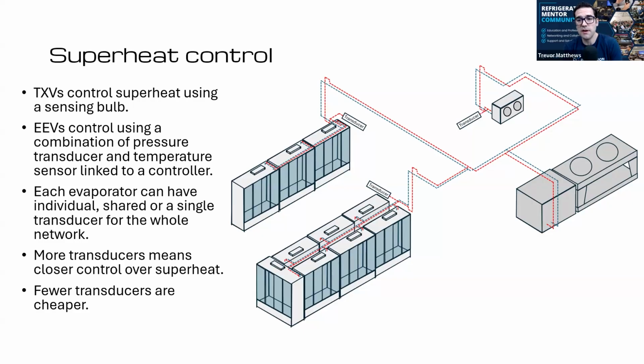Because you've done both, right? And what are your thoughts on the differences? Yeah, so obviously with the new systems, I can dial into a store remotely. On the contract that I was working on, I could look at the fault and potentially diagnose it before the engineer even arrived. It's great for a steer. If I'm seeing flood back, low superheat on something, I can shut it down remotely as well, protecting the compressors, because obviously there's a big cost if you start getting flood back through a cabinet.